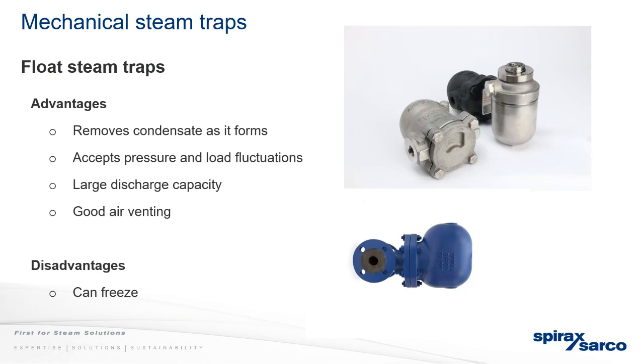Disadvantages: it can freeze, probably not in Kenya or East Africa, but in other parts of the world. That can damage the ball. If you lose the integrity shape of the ball, it may not float, and if it doesn't float, the trap won't open.